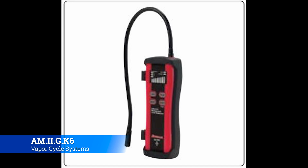You can also take a FLIR gun and just point it, because as the coolant leak comes out, even if it's really, really small, it's going to super chill the area that it's coming out of. And then whenever you get that, you'll get either a white hot or black hot, depending on how it's set up, spot on the system that'll look fundamentally different, especially after it's sat for a long period of time. And you'll know that there is a leak there.